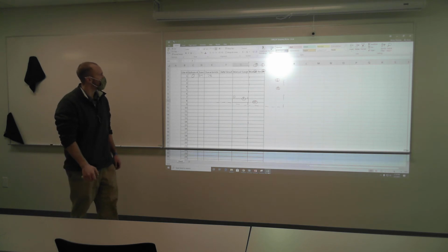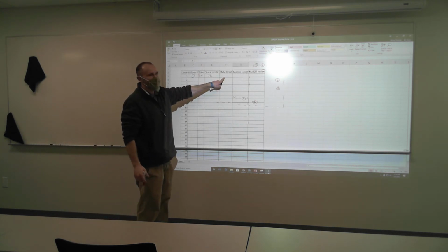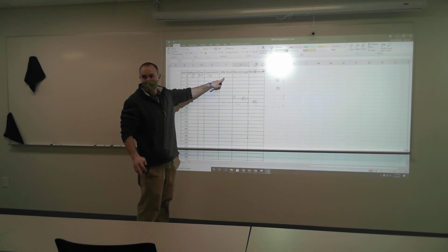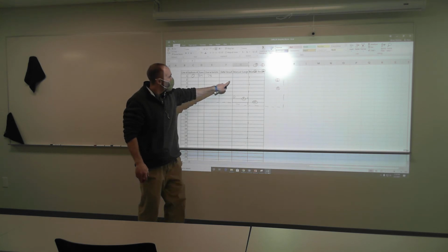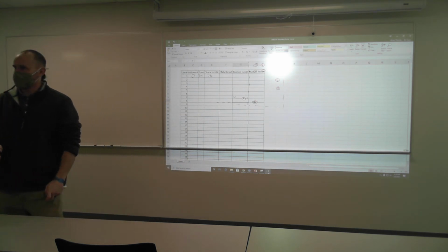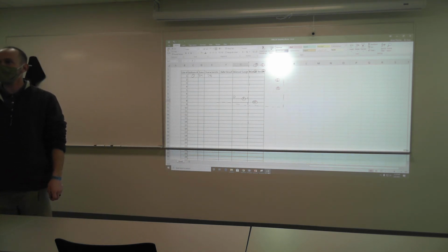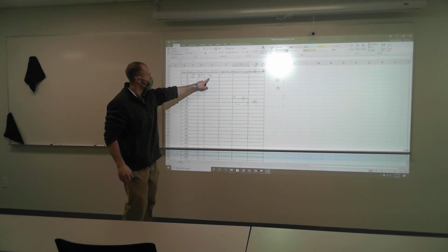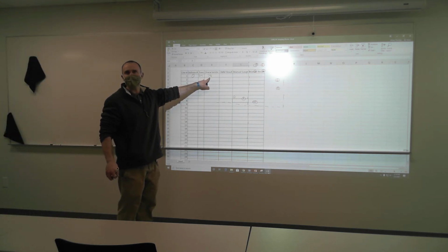Okay. All right, so the CMM result is simple. When you run it on the CMM, it's going to give you a result in the dimension report. All you have to do is fill it out in there. For right now, for your homework, obviously you can't fill that out because you don't know what it is yet. For manual gauge, I just want you to say what type of gauge you are going to measure this with. Now, you have to pay attention to the level of precision of the tolerance. This tolerance is 0.78. What's the plus or minus on that?